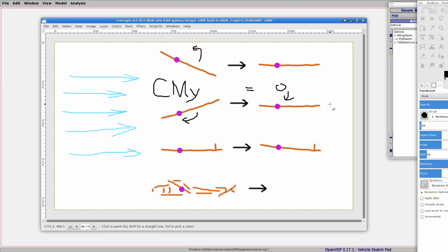For a perfectly flat sheet, a flat plate like that, it's just going to be facing straight into the wind. However, we're not flying perfectly flat sheets. So let's say we had a little bit of something sticking up at the back, like a tail or something. This is going to get in the airflow, and instead of ending up perfectly flat, I think we could again see it's going to end up at this point. So the coefficient of moment being 0 is at some angle. In this case, it looks like an angle of attack of maybe 2 degrees or something like that.